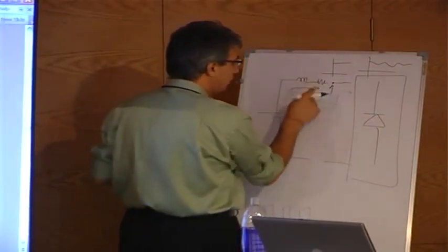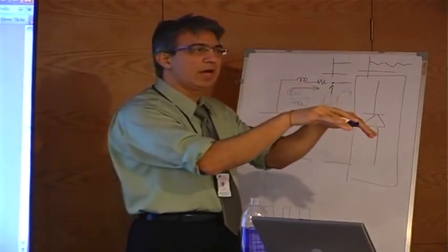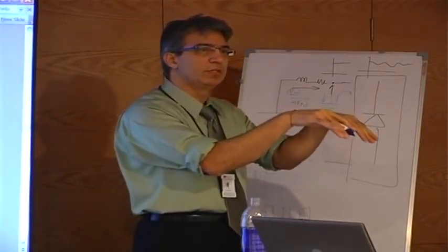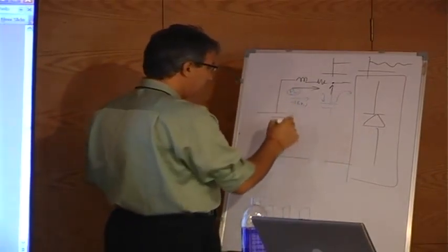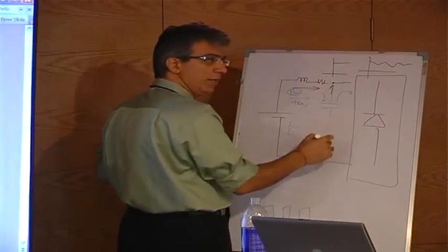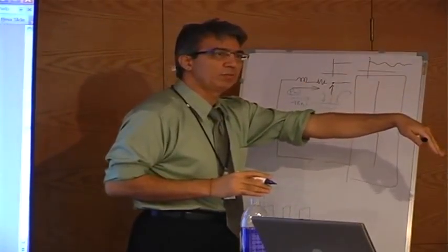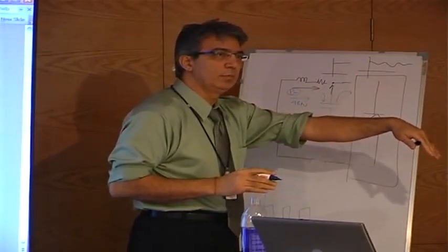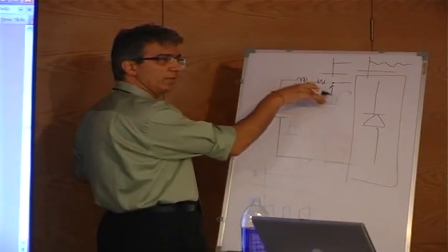It's slowly getting charged here and then providing the filter components out to the inverter when the inverter needs a 20 kilohertz. So effectively, my current in this branch goes to DC when I put this capacitor here. And yes, 49 watts of power is being drawn from the capacitor, but it is at high frequency, and this capacitor is getting that power slowly when it gets charged.